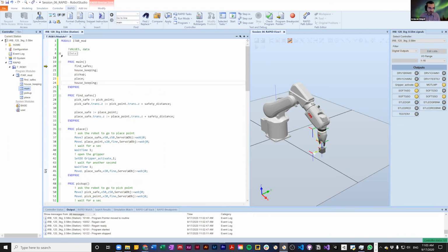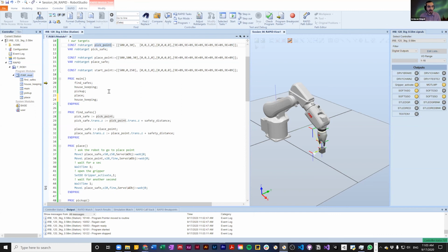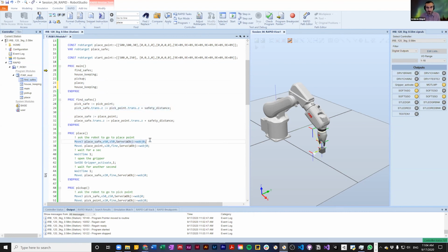So this is the Robot Studio Rapid Programming basics. You understood what is a piece of data, a value, what different types of data look like. For example, we got familiar with numbers, with the tool data that we are usually not touching, and with robot targets, and we learned how to declare and initiate one, how we can organize our code in different procedures, and how we can assign values, update values, and make motion commands.